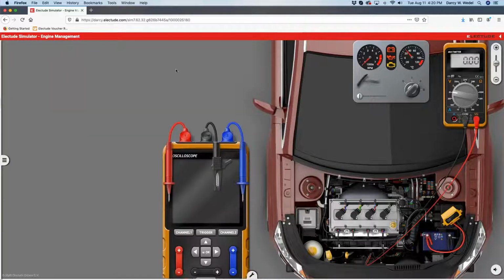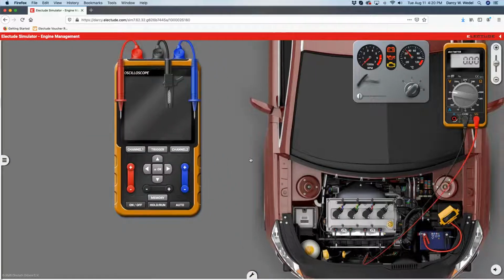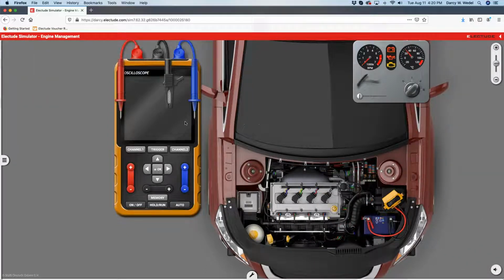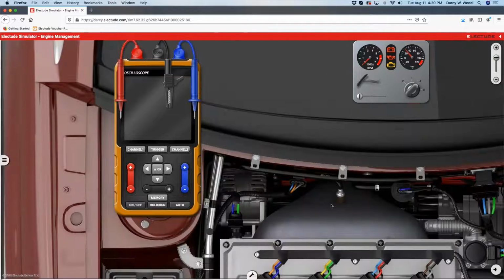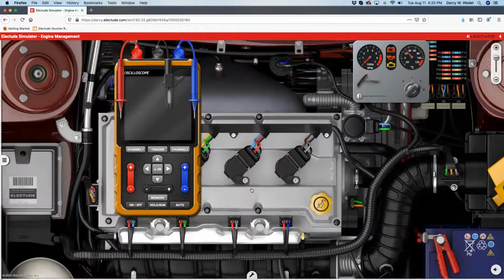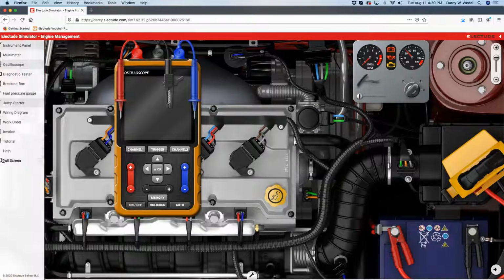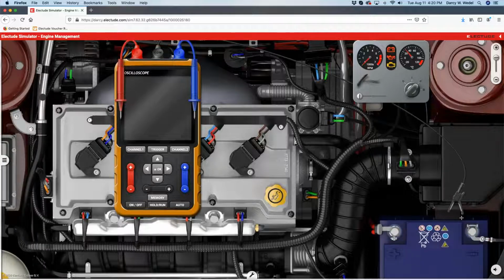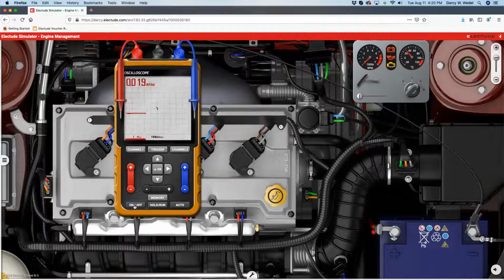So let's look at the lab scope. Very nice lab scope here. So as far as hooking up your alligator lead there, your negative post has to be connected to the battery. So this will always be connected to the negative post of the battery. You can't connect it on a bolt or anything like that. So it always goes here. And we'll turn this on.